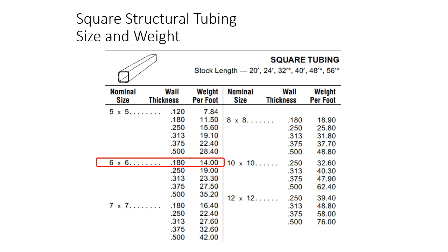And as I said before, all these materials, if you're going to go to a supplier to get tubing or any kind of other steels, they usually have a book that they'll give you. You know, most designers have a copy of these books. So then it tells them the sizes and the weights of the structural tubing and what they need to use, the wall thicknesses, things like that. A lot of useful information. So I think this is more or less used on the other side, the design side of things.